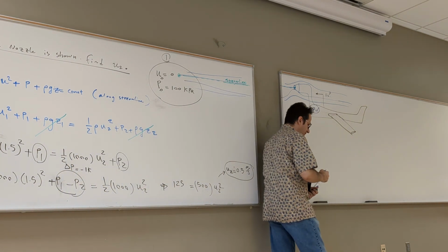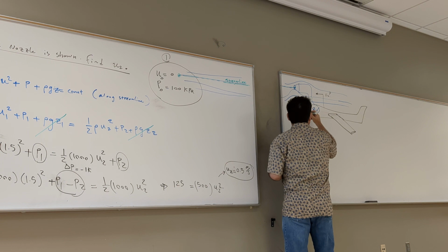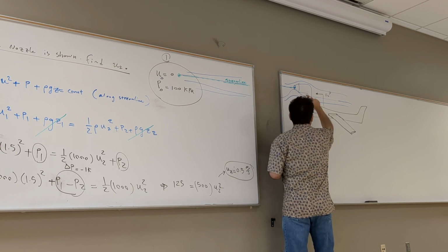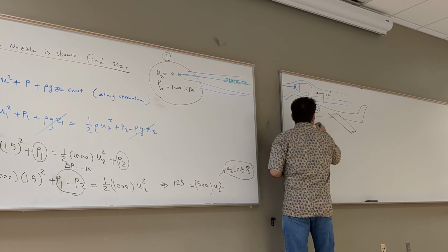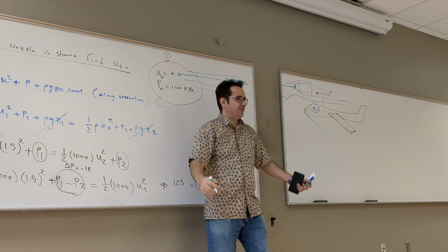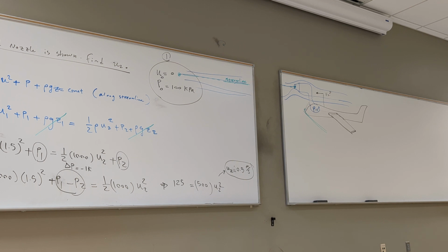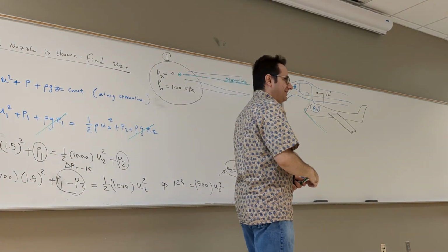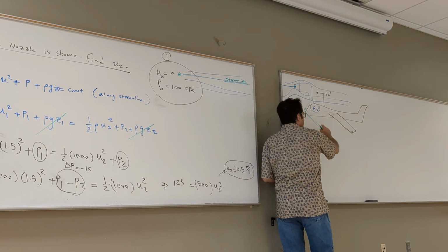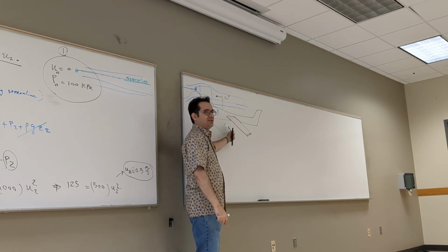with a speed near the speed of sound, then you get something called shock waves, right? There are shock waves. And if you put this probe here, or here, or here on the wing, because you get a shock wave, you have a delta P across the shock wave. I'm pretty sure you have seen that shock wave. It's like when a military aircraft goes fast, and you see it's like a curtain wrap, like a white wrapper around the aircraft. That's a shock wave. So you get a significant delta P pressure drop. So if you put your sensor here, the value it measures is totally rubbish.